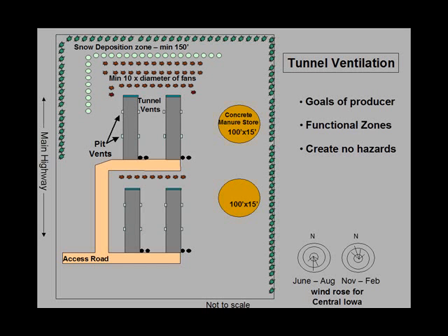Other things to consider, this may be mechanically ventilated, but you still need to have an inflow of air into the intakes to have proper vents. So again, you don't want to completely close off the site to winds that are coming on site, but you can still manipulate things to a degree where it's not going to cause problems in the intake side of things.